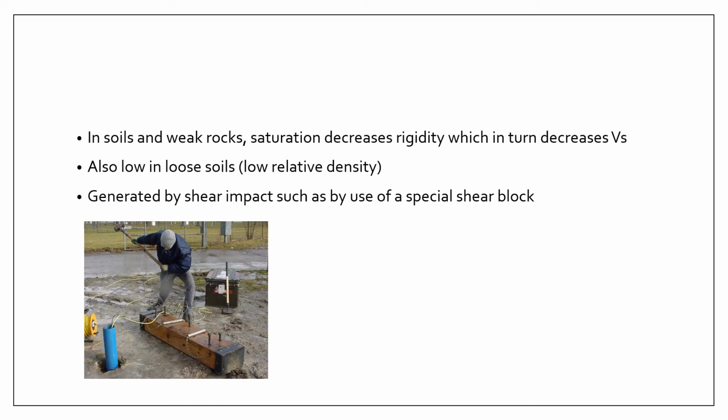It reduces their shear strengths, and in the same manner, introduction of water decreases the shear modulus of your soils and weak rocks, and in turn, this decreases the shear wave seismic velocity. So it's important to distinguish that, because in compression wave velocity, water actually increases the velocity, but in shear wave velocity, for soils and weak rocks, you actually get a decrease.